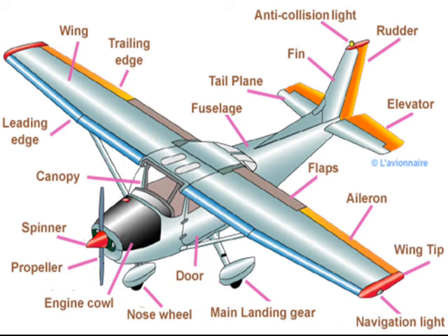The net effect of doing this operation simultaneously is to give a very powerful rolling control to the aircraft about its axis. The function of aileron is to enable the pilot to balance the aeroplane when it is tilted by a gust of wind. It also permits tilting the machine purposefully.